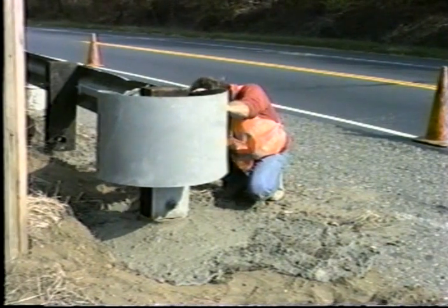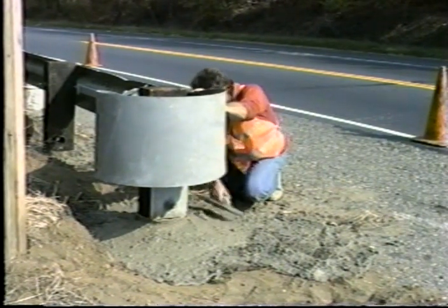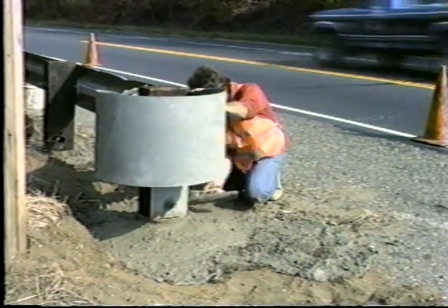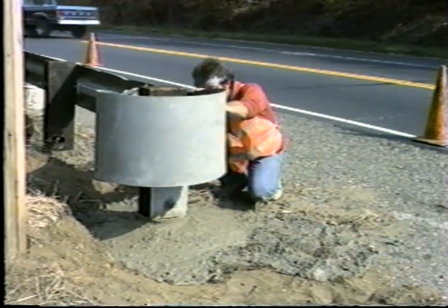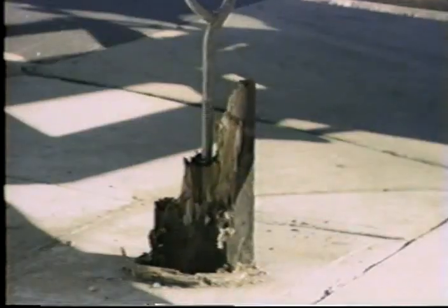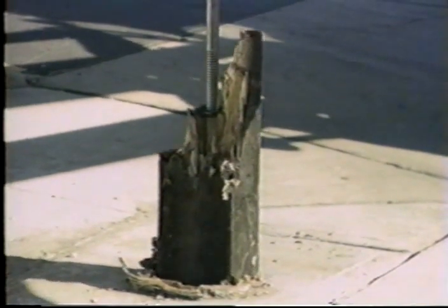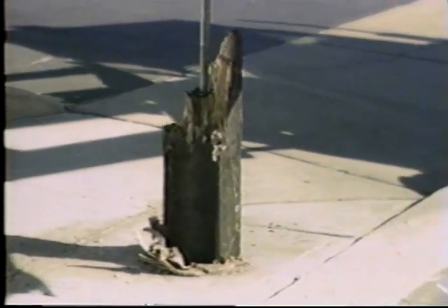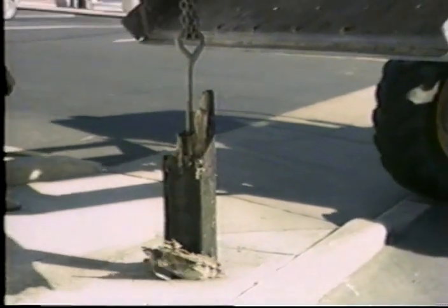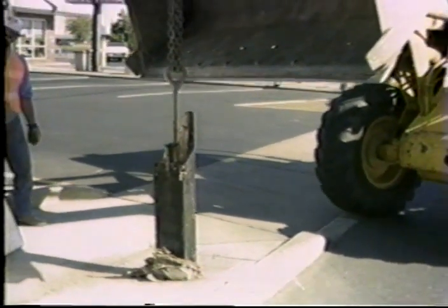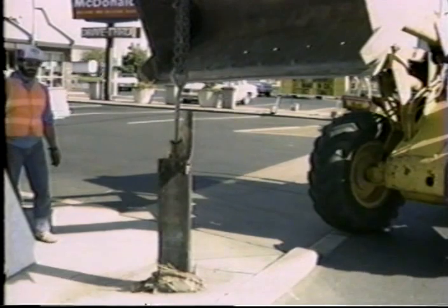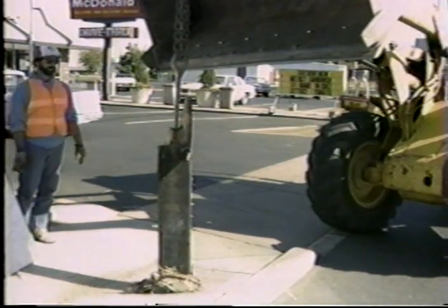Once installed, the paper tube absorbs water from precipitation and is softened so that the post stub pulls out easily. Much of the tube comes out with the stub. The remainder can easily be removed from the hole since it does not adhere to the concrete footing. Stub posts can quickly and easily be removed from this type of footing, which meets installation specifications.